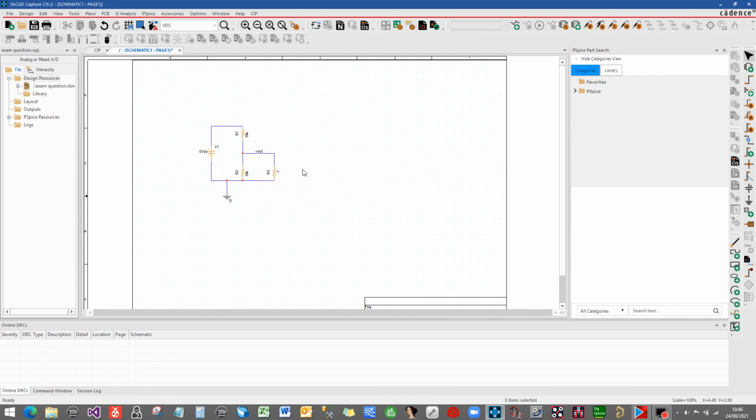So this resistance here basically has to equal the source resistance. This is the load resistance, this is the source resistance. Now out of the 5 people that I interviewed for this question, I think only one person got it right without any prompting. No one else got it right even with prompting. They all worked out that for maximum power transfer to take place, the load resistor had to be the same as the source resistance, but they couldn't work out what the source resistance was.